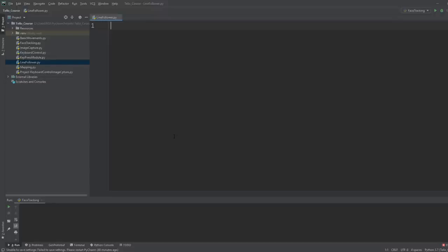What I will do is use my webcam, and once everything is done, we can implement it on the drone. The idea here is that we are going to lay down A4 papers as our path, because it is very simple to find A4 papers and everyone has them. So this will be a very easy way to create a path. We will be using A4 paper, but you can use anything that you want. One good thing about A4 paper is that it is plain white, so we can use color detection to detect our white color. So let's get started with that.